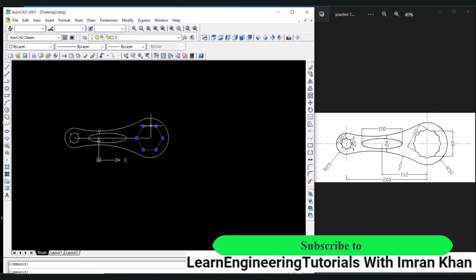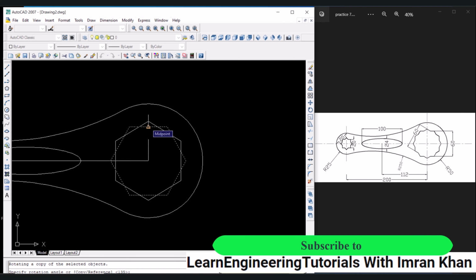Enter. Again, click on this hexagon, click on rotate option, select this as the center or base point, and now copy rotate again. So C, enter, and this time click on this midpoint.